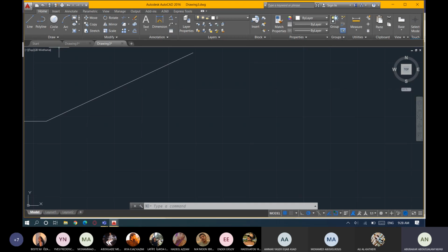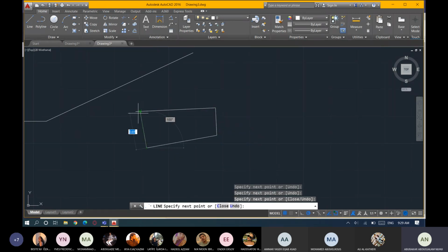At the same time, let's have a look at the rectangle. We have seen a line. Okay, polyline. So polyline is just a command which is kind of like a line, but the only difference between polyline and line is one thing. Line treats each and every line you draw as a single line. Okay, guys? This is what it does.